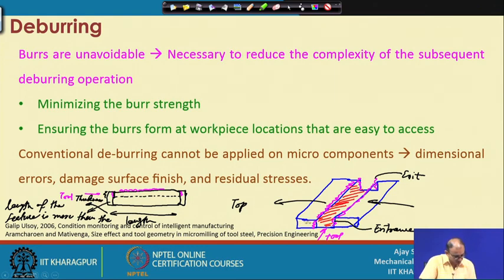So, here what is happening is that the thickness is very small for whatever features we want to create, but we have more length in this case. The problem is that if the thickness is small, it is difficult to maintain that thickness throughout the component if you apply a deburring, lapping, or any other polishing operation. It may actually damage the thickness here. Even 1% change in this particular thickness sometimes creates a problem in the functional requirement.